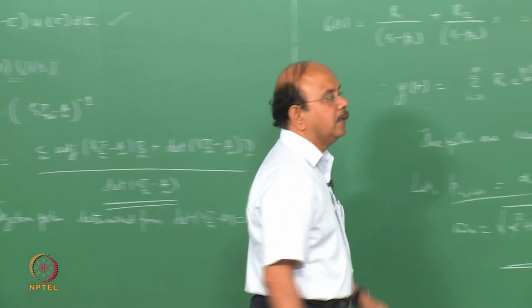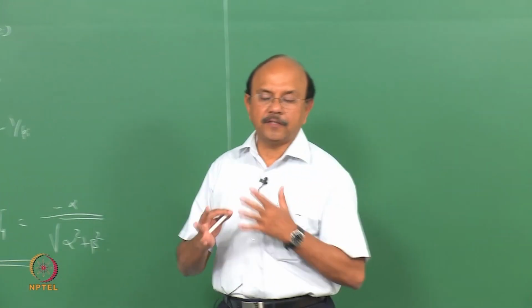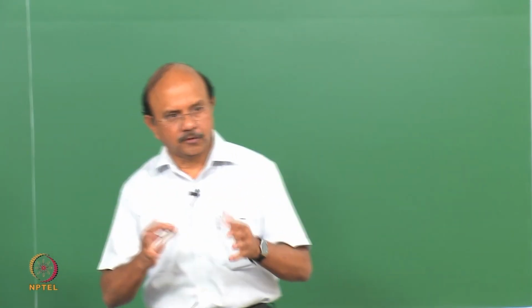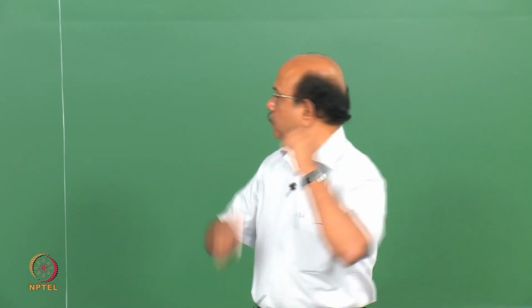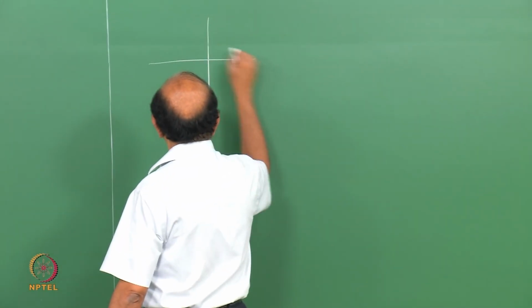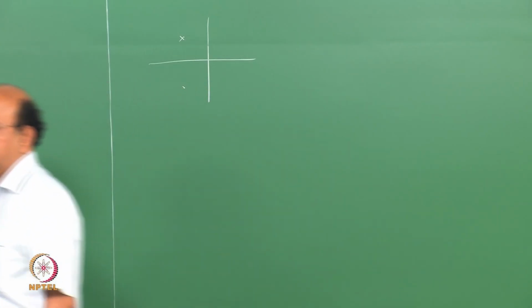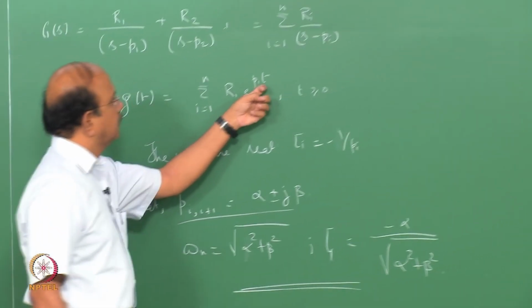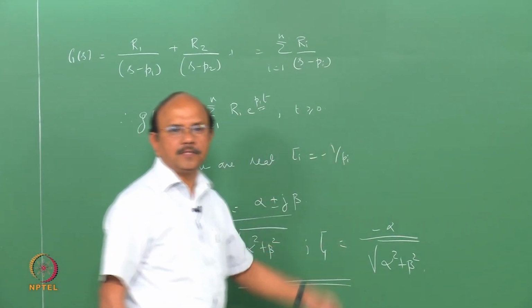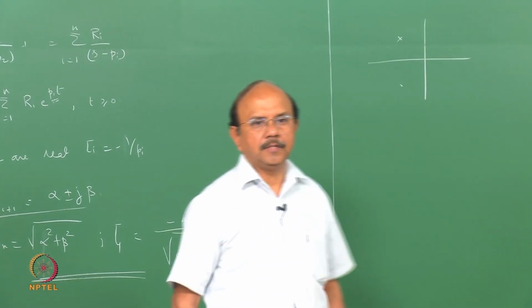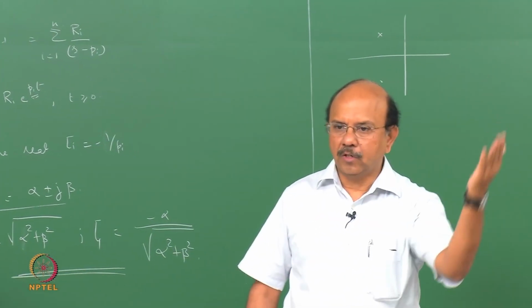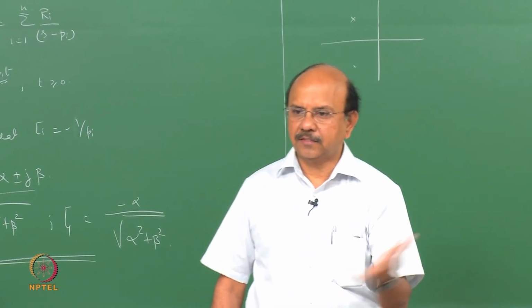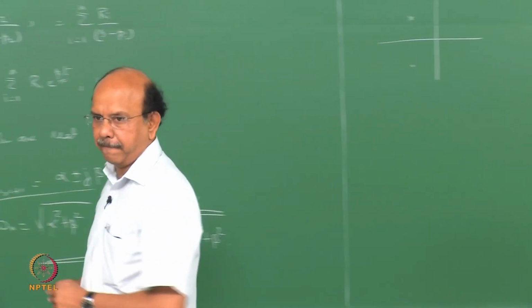What are important. Okay. Further than this, about the effect of poles, you all know it, and that you know that in the S plane, okay, if this is the left of the S plane, then if the poles are situated in the left of the S plane, the system is stable, basically because you have this e power term here, and hence when it is negative, the e power minus term, minus into t, would now start decreasing with time, and hence the system becomes stable.